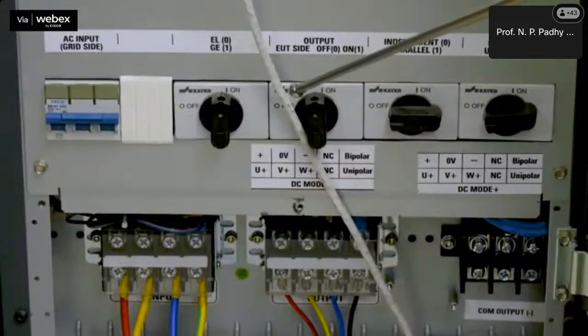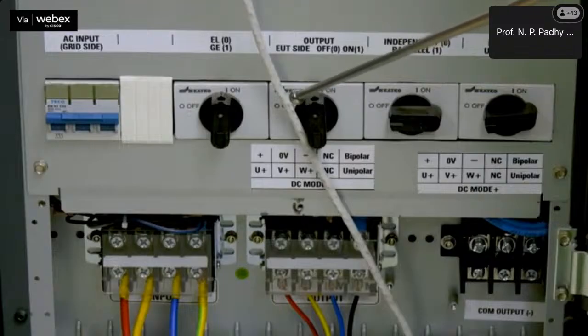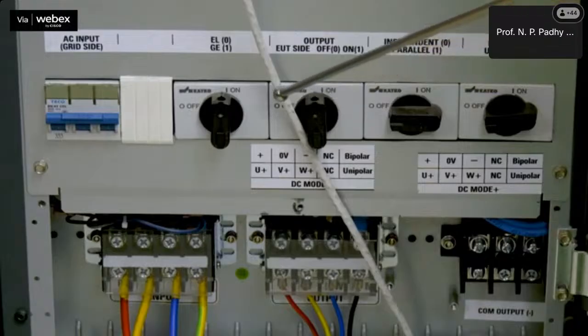Initially, the device working mode switch is at 1. This represents that the operation mode of the device is DC. By configuring the 4 switches, the functioning of the device can be modified. After configuring it in DC mode, the switch combination decides various functions such as DC source emulator, DC programmable load, battery emulator and PV emulator. In this video demonstration, we are very interested in showing how to configure it as an AC grid emulator too.